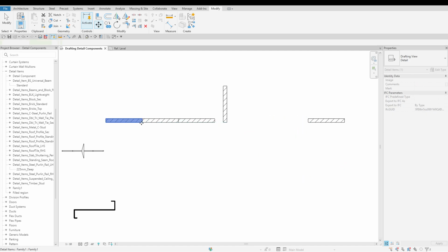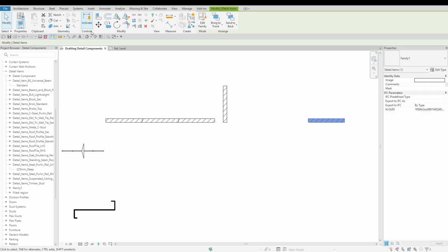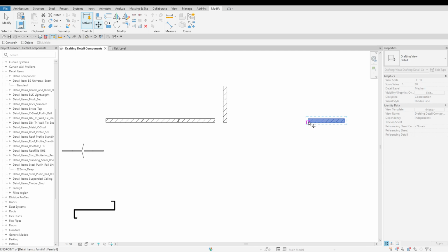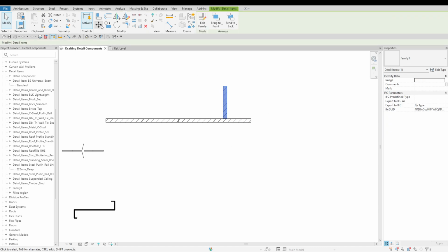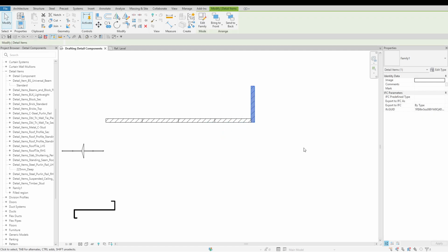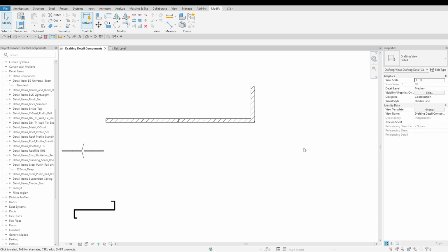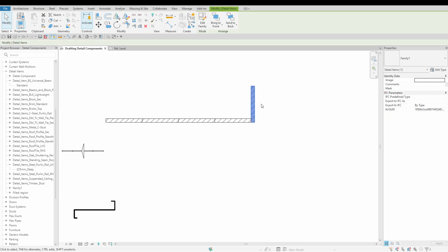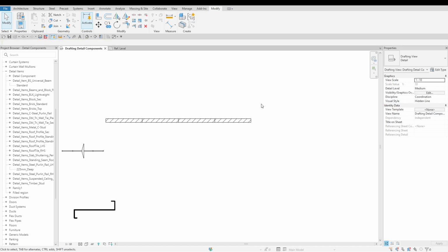Revit also allows you to create a 2D line-based detail component family, which can be especially useful for representing continuous materials such as insulation, cladding, or sheathing. With this type of family, you place the detail by selecting a start and end point along a line. For example, if you're adding a plywood fill pattern in a section view, selecting the 2 points places the component with the thickness and fill pattern defined in the family.